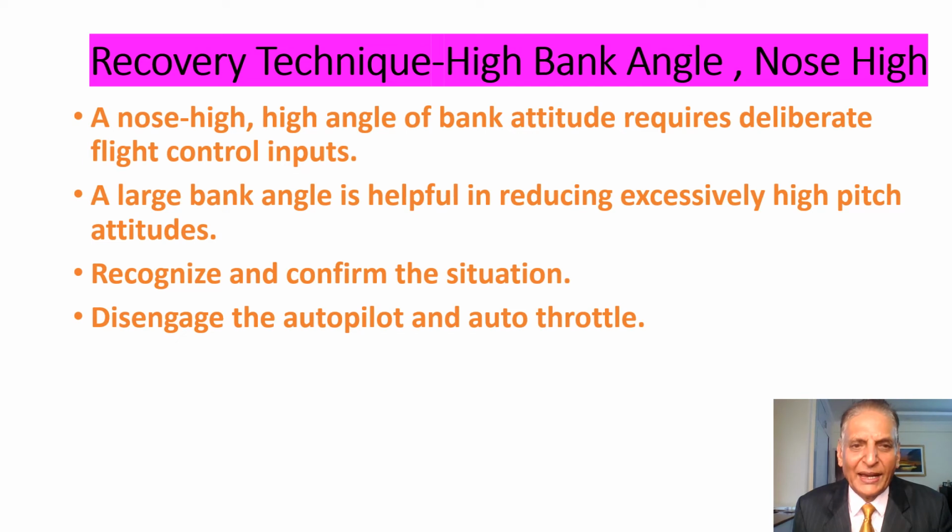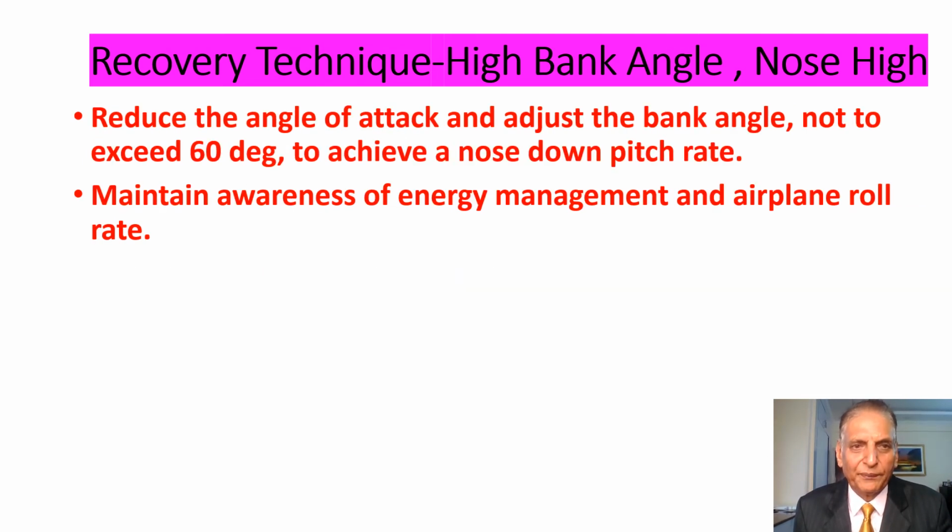Pilots must recognize and confirm the situation. They should disengage the autopilot and auto throttle. They should reduce the angle of attack and adjust the bank angle not to exceed 60 degrees to achieve a nose down pitch rate. Maintain awareness of energy management and airplane roll rate.